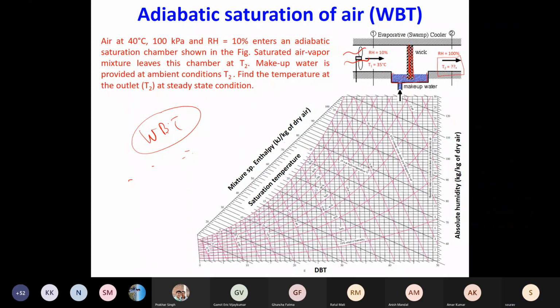Okay, in a desert cooler, you may not have complete saturation, because just like heat transfer, mass transfer also requires a lot of area. In order to have perfect mass transfer so that you saturate the incoming air, you will require infinite area between the incoming air and the liquid droplets. So you cannot provide infinite area.